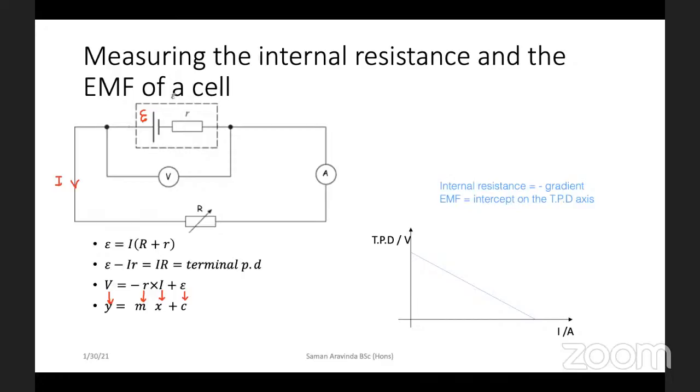At a certain variable resistor value, the power output becomes maximum. I will show you that when the power output becomes maximum, the external resistance equals the internal resistance. Using differentiation you can prove that, but you don't have differentiation. I just wanted you to do the graph and identify that.